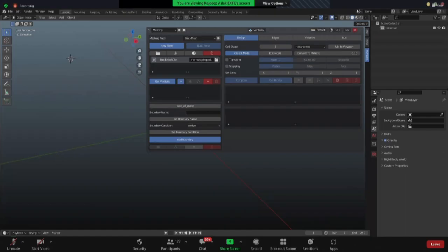Okay, so someone is saying unable to locate the new mesh through select mesh file path. Vinay, maybe you can click on that red colored button. What that will do is it will just delete it from your memory, and you can create a new mesh file path again. Maybe try that, and the same process.